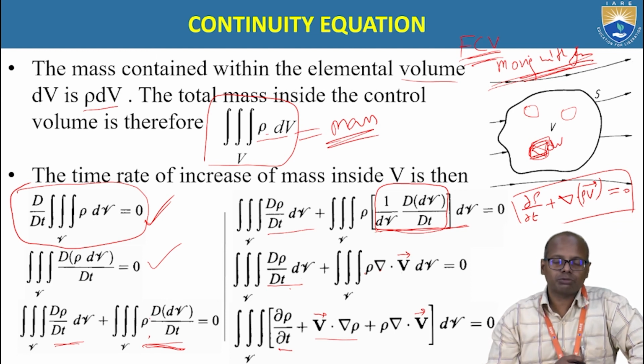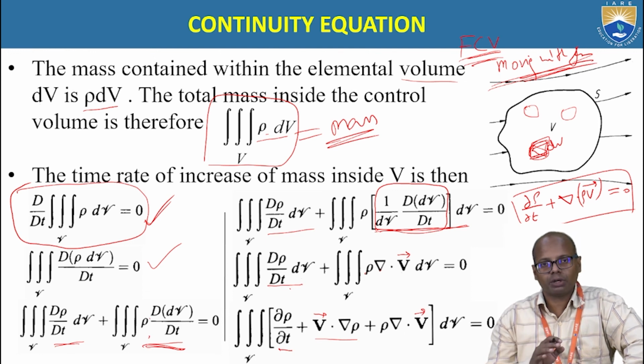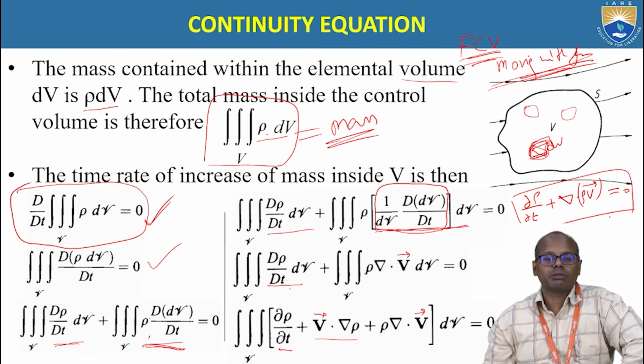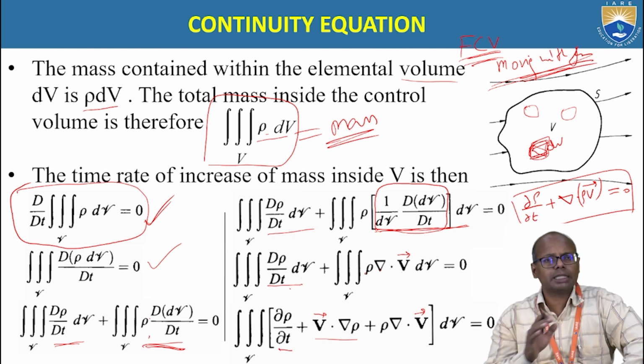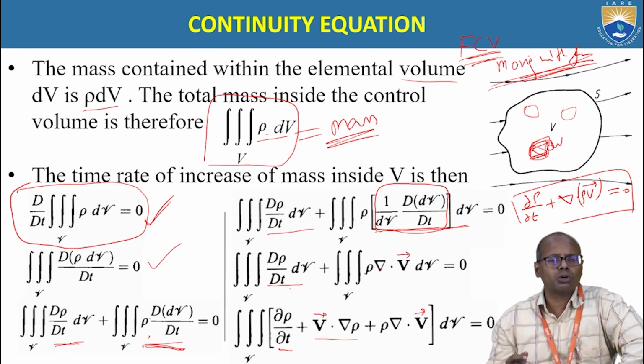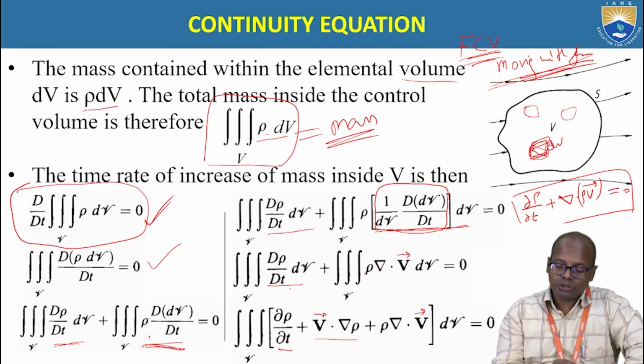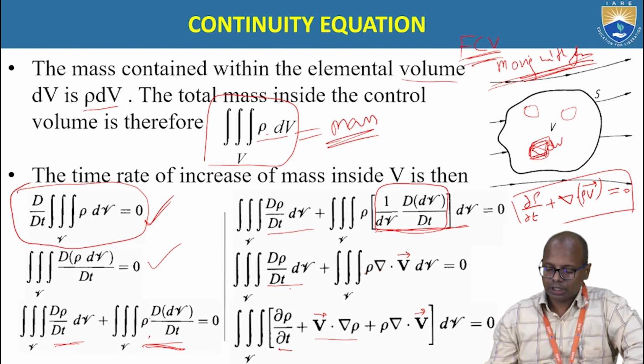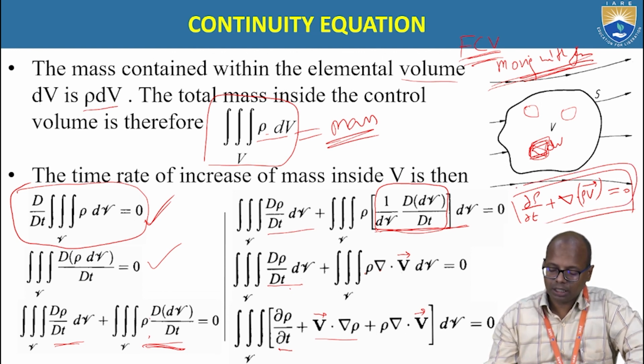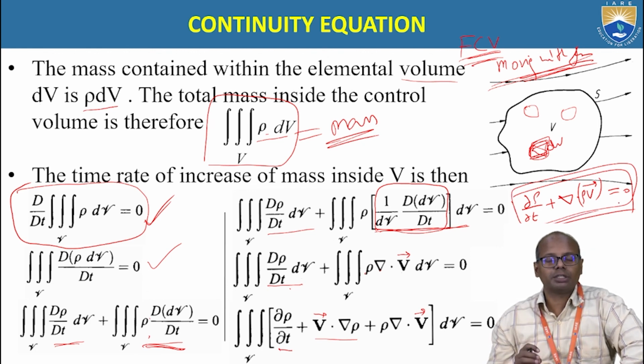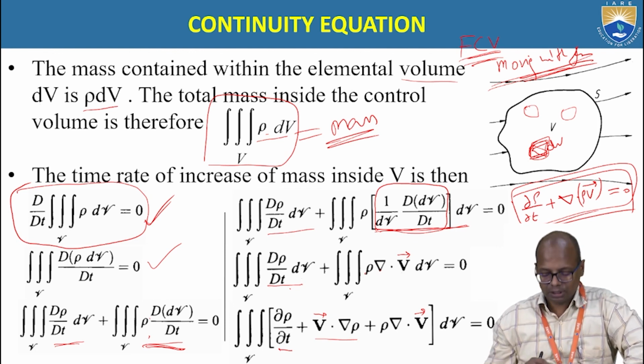In the previous case, we initially got a non-conservative form but differential form, and finally we converted it into the conservative form. So from this exercise of doing the 4 models, what we can understand is that using any of the models, we can finally obtain the continuity equation in differential form, which is a conservative form. So that is about the continuity equation.